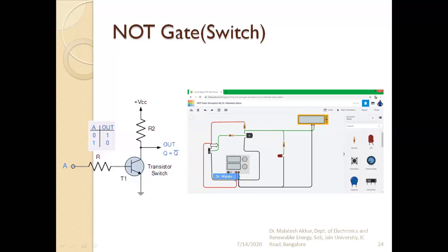Okay. So here, this is the switch now. This is the middle terminal or the common terminal, what we call it. Upper side of this, 5 volts is there. Lower side of this, 0 volts is there. So by sliding it down or up, we can apply either 0 volts or 5 volts to this A. Let's call this A. Okay. And only this circuit is enough. This is the extra part.